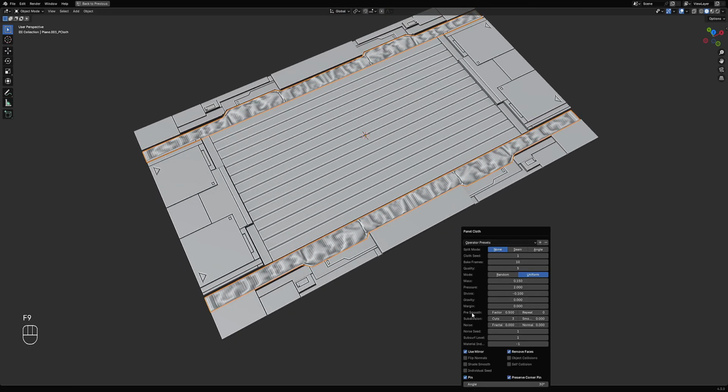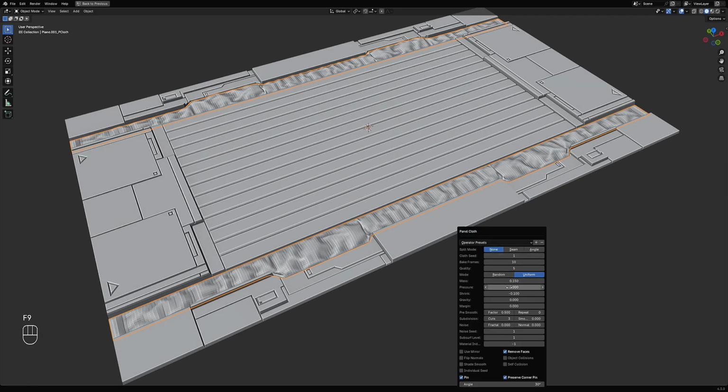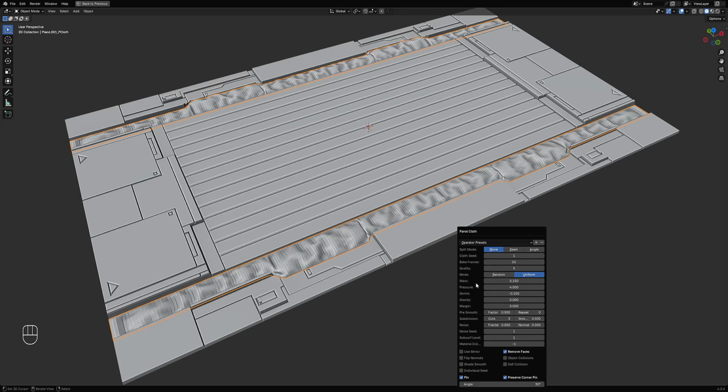You can try to get rid of the symmetry by disabling use mirror, but it's going to be slower because it's using all of the mesh and not just the split half because of the mirror. So using the pressure, let's try and make this puff out more. I think it's going to be shrink minus 0.2, not that. I think it's pressure and also mass.